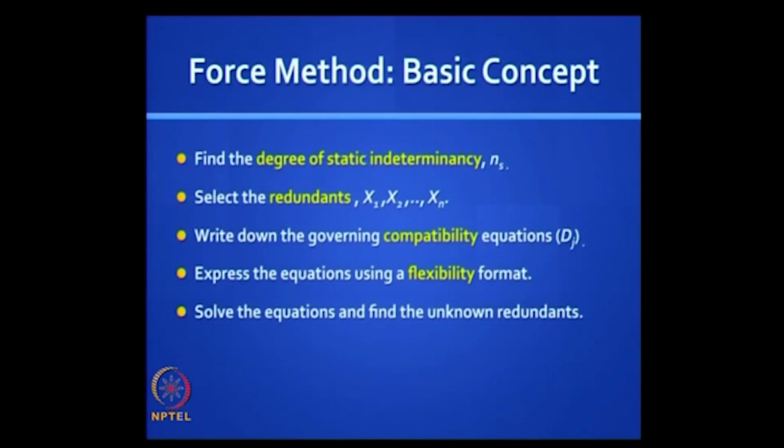to xn. Once you found x1 to xn, if you draw the free body, you have got a statically determinate system. You can analyze it, draw the shear force diagram, draw the bending moment diagram, or find the actual forces in the case of a truss. You could do it directly on that overall free body. Alternatively, you could find out what is happening under the action of each of those loading systems on the primary structure and superpose everything. And so you find the complete force response. It satisfies equilibrium, but more important, it also satisfies compatibility.